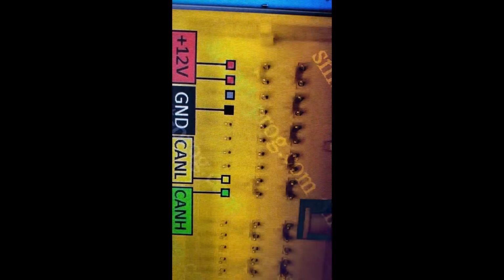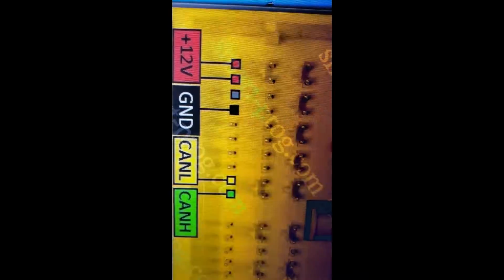8635A26, and that's the same one, 8635A426, and the airbag that we have the crash on is 95640, and that's for the pin CAN high, CAN low. And then if you go for the airbag, when you measure, I have power already to it.